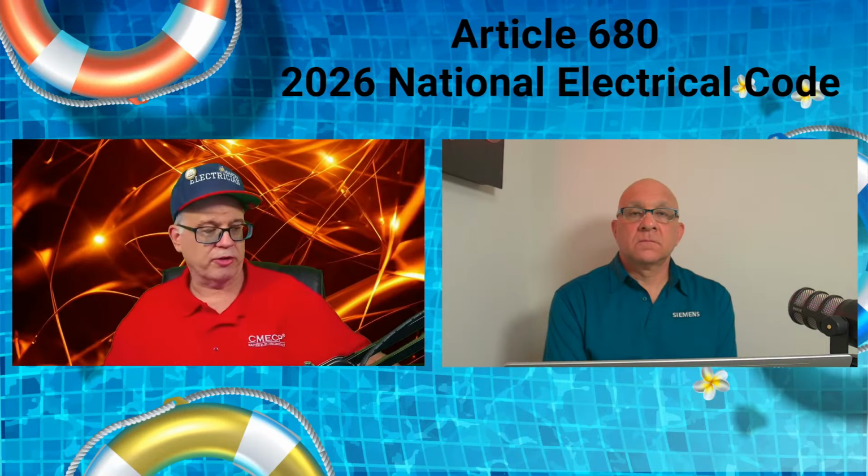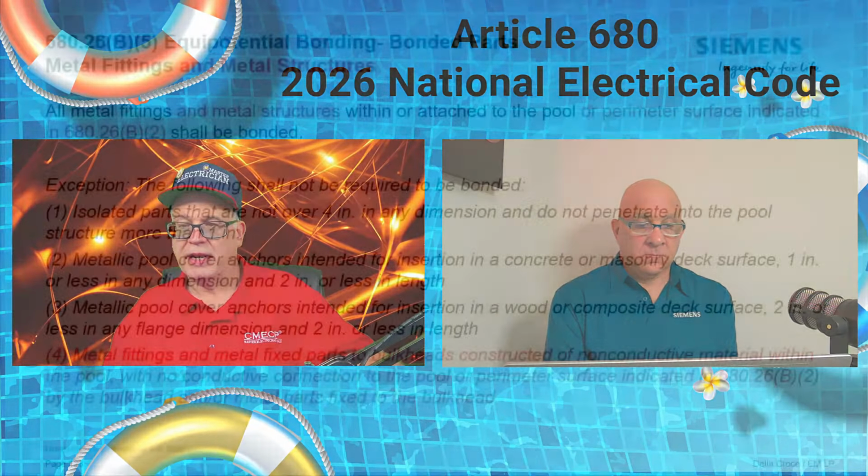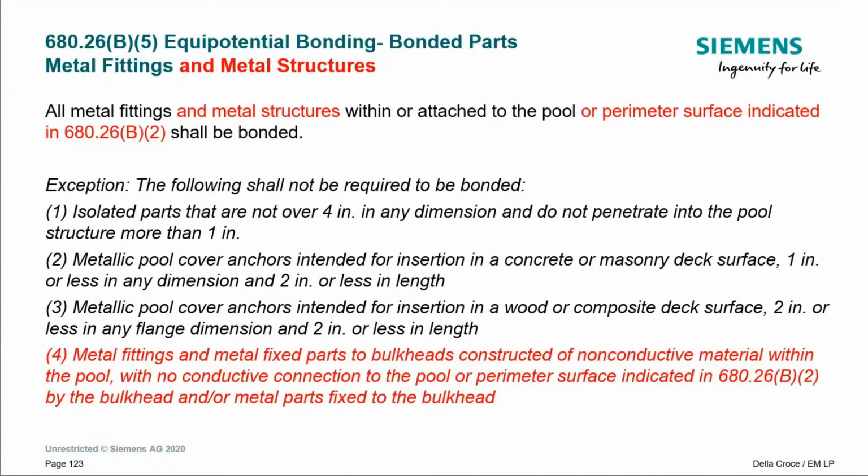Next, we have the third one. Same thing: anchors intended to be inserted in wood or composite decking, 2 inches or less in any flange dimension and 2 inches or less in length. So with this one you get a little bigger, a little more, right? But the length of it going down into the deck is still 2 inches or less.